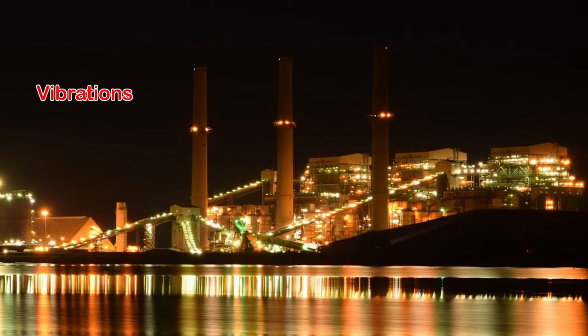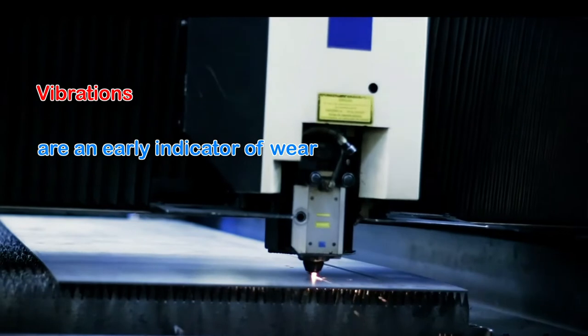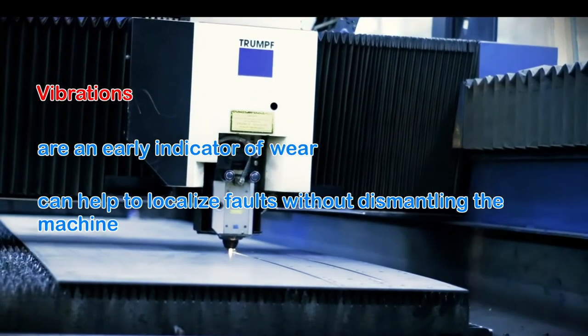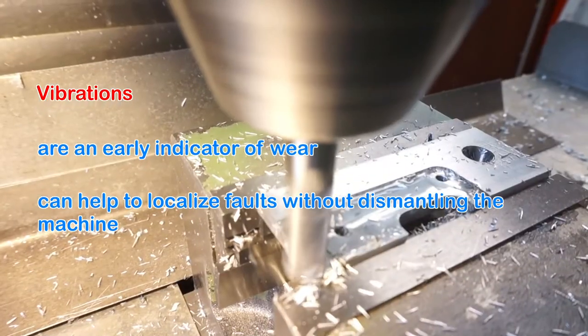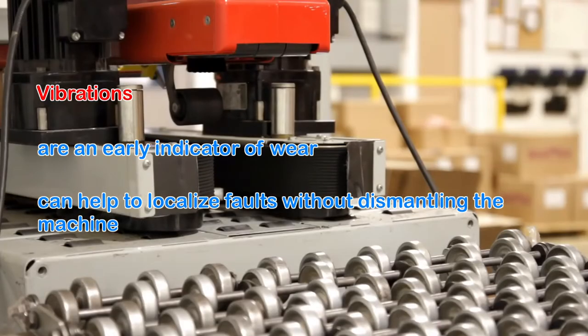Vibration is an early indicator for wear. For example, bearing problems can be detected at an early stage, by measuring vibration acceleration, without dismantling the machine. Changes in the vibration spectrum can be recognized long before they become perceptible, or audible, for humans.